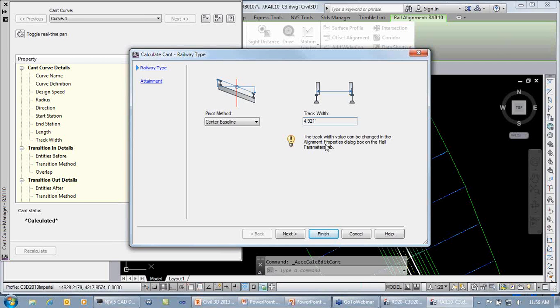Let me rephrase that. I'm a little confused by this because most railway, the width is specified based on the gauge of the railway, which is measured inside rail to inside edge of rail. And in this dialog and in the alignment definition, they're actually doing center to center. So it's a little confusing. If you look at US gauge, it's not 4.9 feet, it's like 4.8. I forgot the exact unit here. So you do have to do a little conversion knowing what your rail top width is. So not real expert on that. But just kind of want to point out what can be done here.